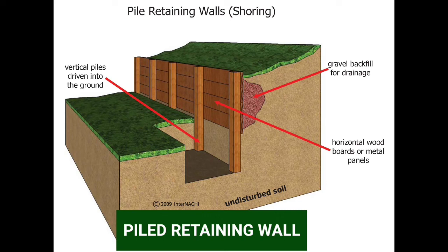Next point, sheet pile walls are built using steel sheets driven into a slope or excavation up to a required depth, but it cannot withstand very high pressure. Next point, sheet pile retaining wall is economical up to a height of 6 meter.